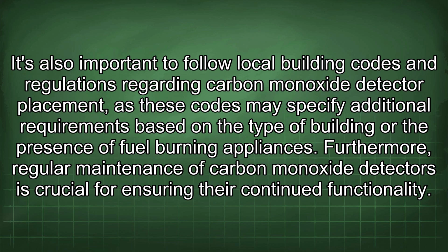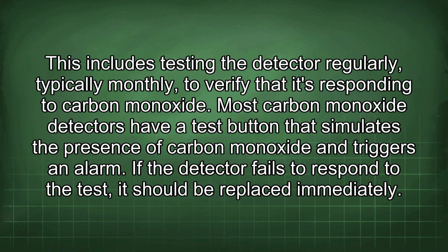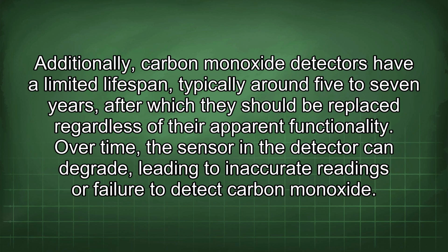Furthermore, regular maintenance of carbon monoxide detectors is crucial for ensuring their continued functionality. This includes testing the detector regularly, typically monthly, to verify that it's responding to carbon monoxide. Most carbon monoxide detectors have a test button that simulates the presence of carbon monoxide and triggers an alarm. If the detector fails to respond to the test, it should be replaced immediately. Additionally, carbon monoxide detectors have a limited lifespan, typically around 5 to 7 years, after which they should be replaced regardless of their apparent functionality.